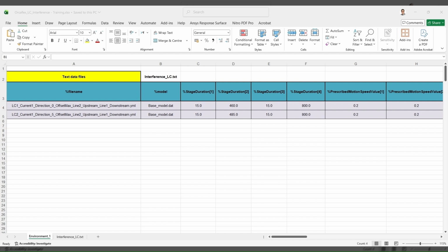Therefore, if the VIV analysis is used to generate DAF values for the interference model, the buoyancy module section should be represented discretely in the interference model. For example, using clamp type buoyancy modules at the actual module locations. This keeps the line shapes, local hydrodynamic properties, and section specific depth application consistent between the VIV analysis and the interference analysis.